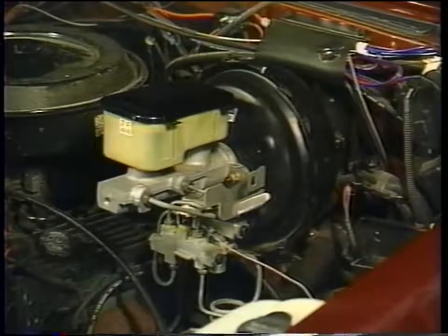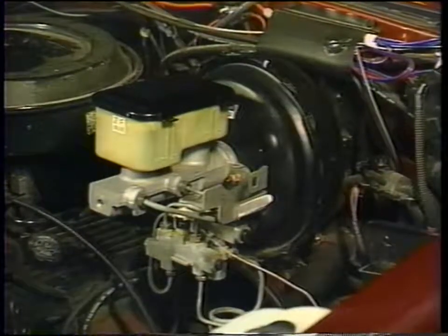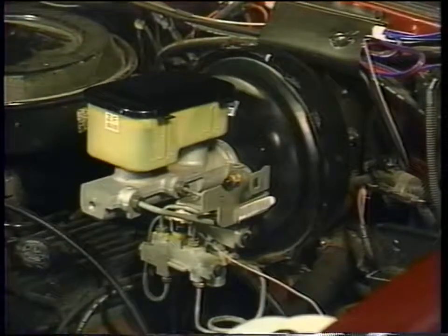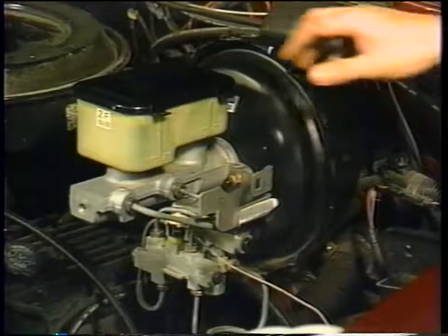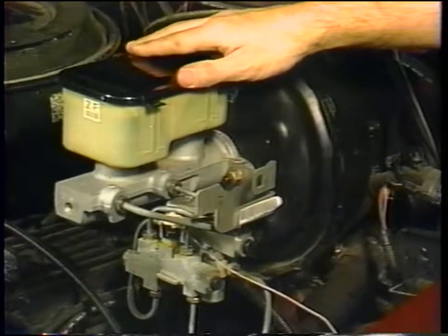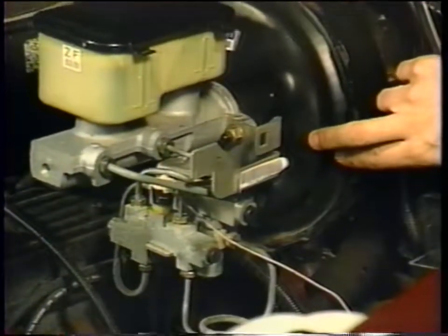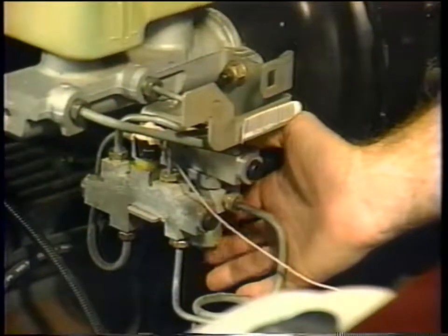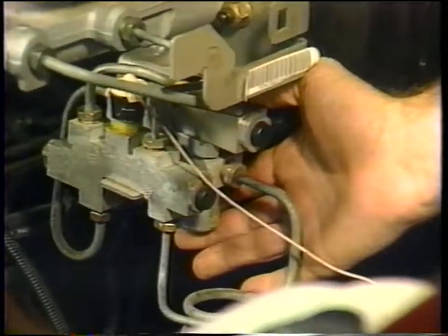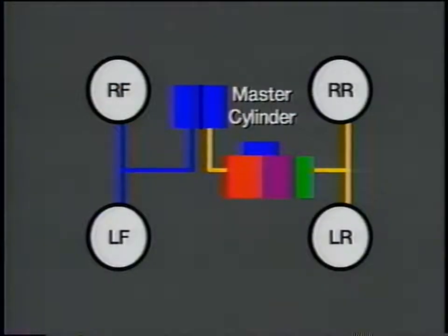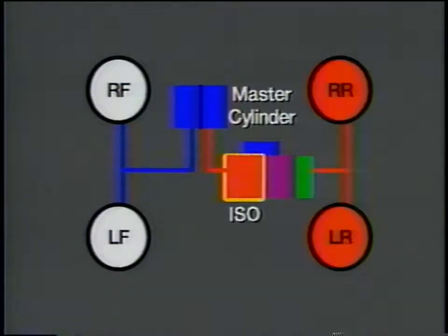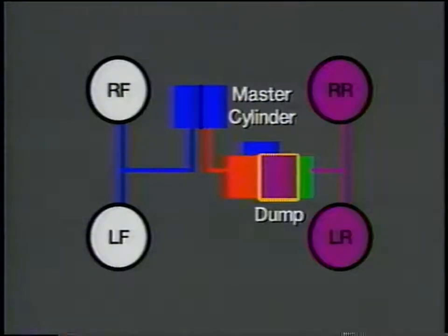The Kelsey Hayes RABS, R-Wall, and ZP R-Wall systems are non-integral rear-wheel only anti-lock brake systems. The conventional master brake cylinder and power booster supplies brake pressure to a dual solenoid control valve for the rear brakes. This unit contains only 2 solenoid valves, an isolation valve to block pressure from the master cylinder to the rear brakes during anti-lock braking, and a dump valve for relieving pressure.